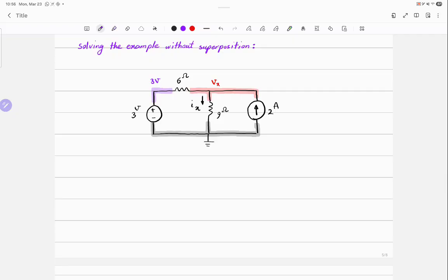What should I do, the way that you've described it? Can I just write a KCL at Vx? Let's write it and see what happens. Let's start with Ava. Can you start the KCL, please? At Vx. Remember, we write all the currents going into or leaving that specific node with the convention that entering is negative, leaving is positive. And remember the red box.